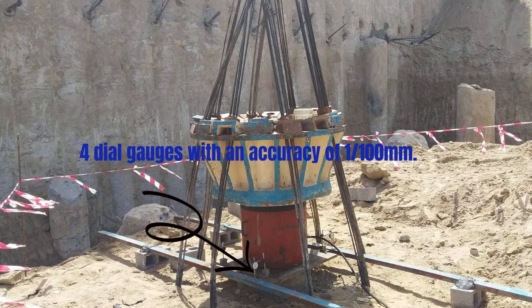Dial gauges shall read directly to 0.01 mm and have a stem travel of 50 mm to 100 mm, with readings included with settlement. Level readings will also be taken by a level instrument on the reaction pile and the beam.